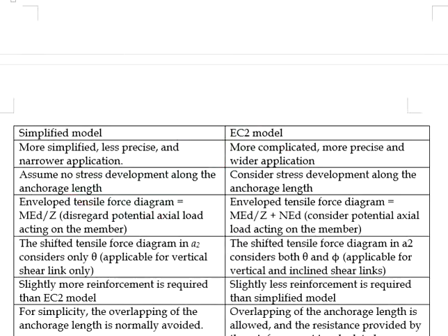To make it simple, the simplified model is only applicable for members not subjected to any axial forces. The envelope tensile force diagram is derived fully based on the bending moment diagram divided by the section properties.